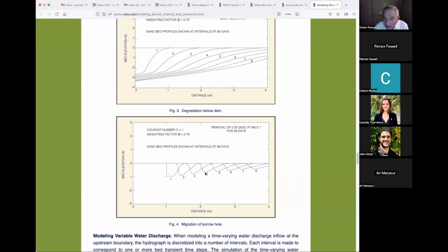The problem was that I was looking at one-dimensional flow, and I was using the one-dimensional equation. He was using a process called head cutting, which is essentially three-dimensional. In other words, because of this drop in here, there's always going to be head cutting in here because of the cataract, the fall that will form in here. So there's always going to be head cutting, but the head cutting will find its own equilibrium and it will stay there a long time.